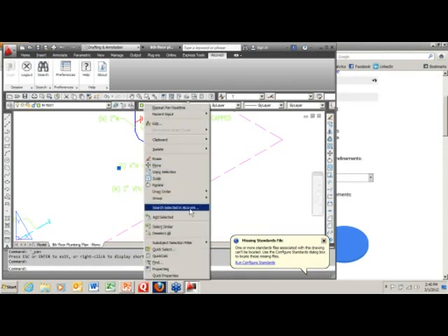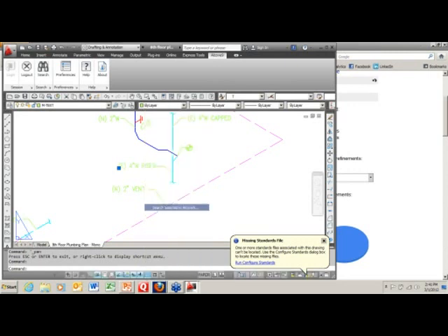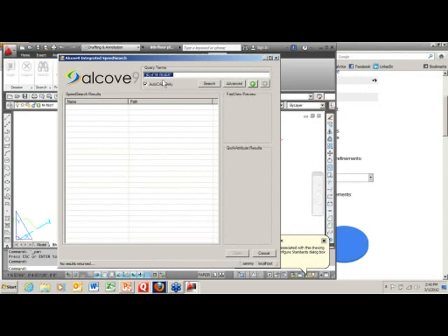and you can see we built in a search in here for Alcove9 right from the drawing. So you don't even have to type the search string that you're looking for. If you have it on a drawing, you can just select it. It substitutes that in there. You can edit it if you have to. If you're just looking for the word riser in there, you can edit that in there, and it'll show you wherever that word appears.